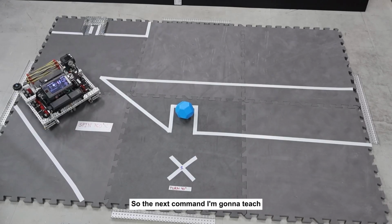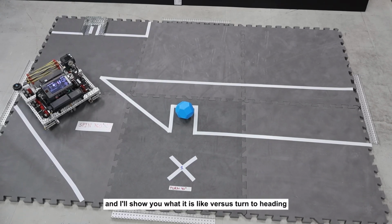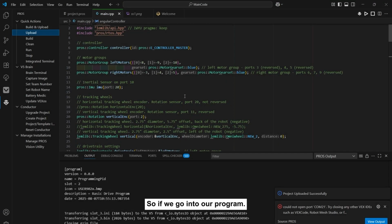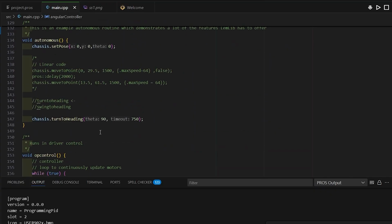So the next command I'm gonna teach is the swing to heading command, which is useful for tight corners like the one that the robot's in right now. What it does is it only moves one side of the drive base, so the robot kind of swings off center a bit, and I'll show you what it is like versus turn to heading. So if we go into our program, and then we can comment this out.